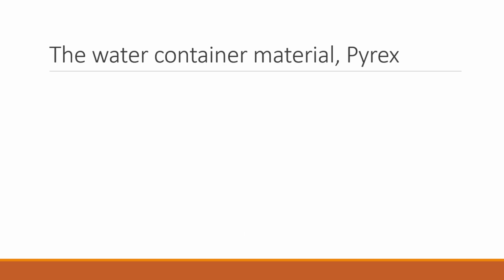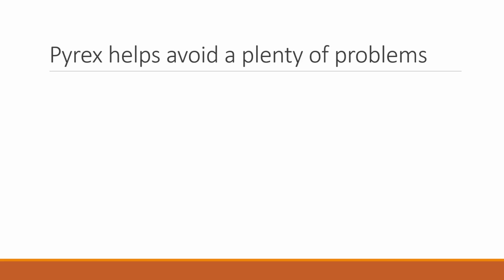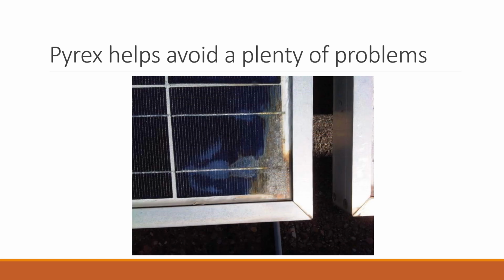The water storing layer, or the container, can be designed from Pyrex, otherwise known as borosilicate glass, such that overheat and high pressure won't cause any cracks in the layer due to the big temperature differences between day and night, to prevent the water from leaking out. Pyrex would be of great advantage to avoid any delamination and internal corrosion caused by moisture finding its way through the panel's cracks. Pyrex is known for its low thermal expansion coefficient, which makes it more resistant to thermal shocks.